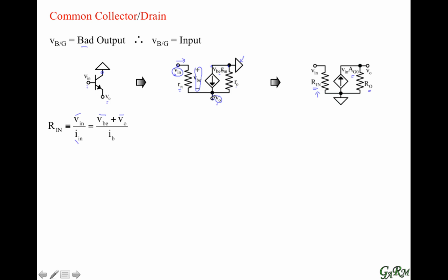We're going to connect a circuit to the output that is going to present an equivalent load resistance, and we're just going to call this RLD for the equivalent load resistance. When we look at the output voltage, we note that that load resistance is in parallel with the output resistance, little ro, because they both connect from the emitter to AC ground.